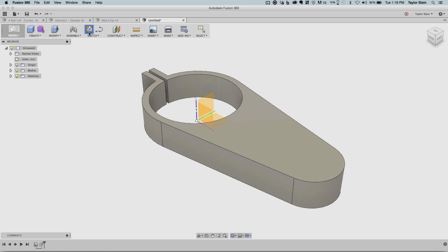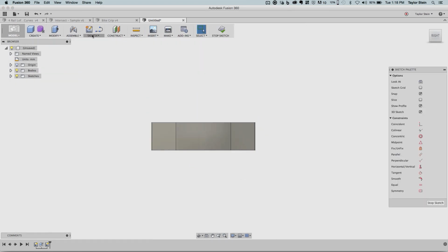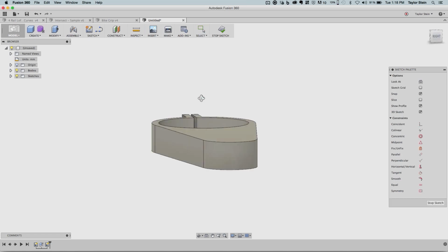Simple way is I can create a new sketch on this work plane, and I can choose the center diameter circle tool here, and it looks like I could draw it. I can eyeball it in the center, but more often than not, eyeballing it's not good enough. It should kind of give you an uneasy feeling, and you should feel like, yeah, there's a better way to do this. So how about before we draw the circle, if we project in this face into our current sketch?